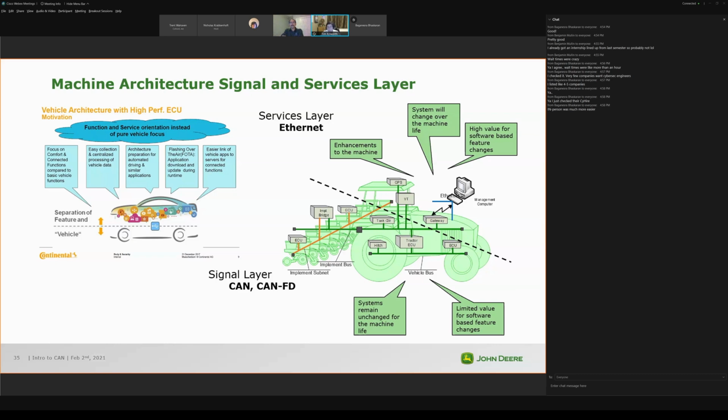So handling the network and each individual message is not an issue. If we look at some of the processors used above, in the services layer, we always have to have an interface to handle CAN, because those processors aren't very good at being interrupted every few milliseconds or even within a millisecond to handle the messages, and you can really eat up a lot of overhead in how CAN is handled on those processors.